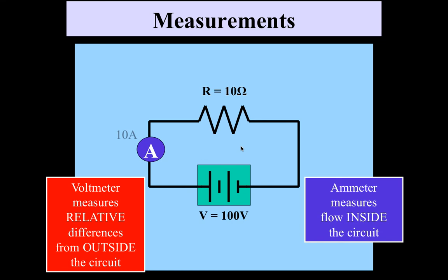No matter where you are in your circuit, you must have a current flow if your circuit is closed, meaning that you have wires connected all the way around from one end of your battery all the way to the other. Anywhere that you place this ammeter in your circuit, you should read 10 amps. This is a very basic circuit, only 2 components. That means that my circuit will have 10 amperes flowing throughout the entire thing.